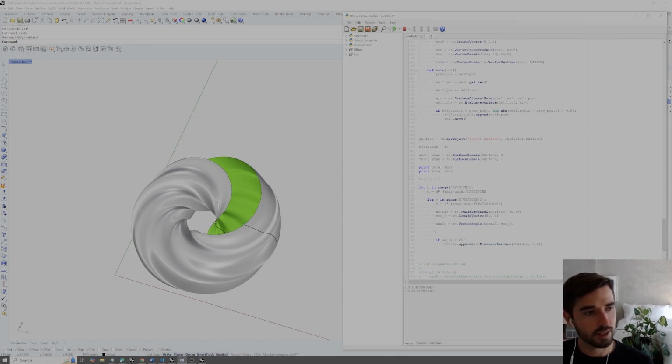And one last thing that we want to do here is add the randomization. We want randbool, so random boolean, equals random.randint. What do we want to feed in here? Either a 0 or 1 value, so 0, 1, and it will choose either a random value of 0 or 1 for every single parameter on this particular surface.